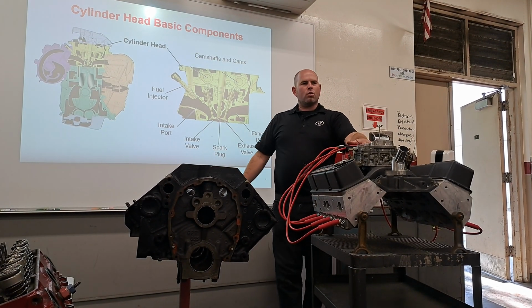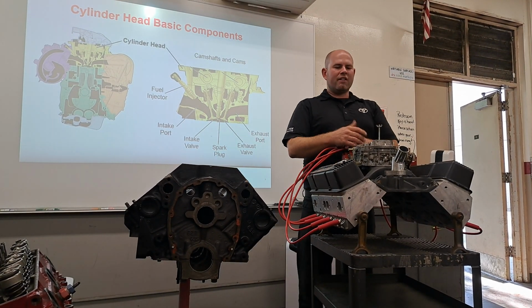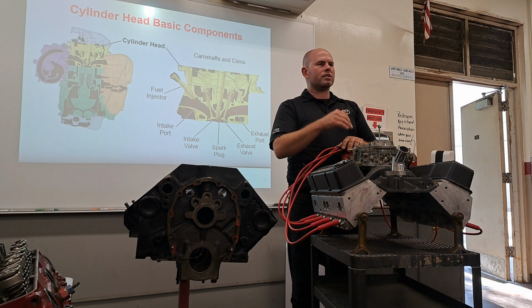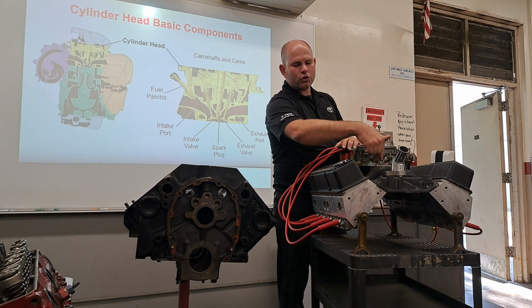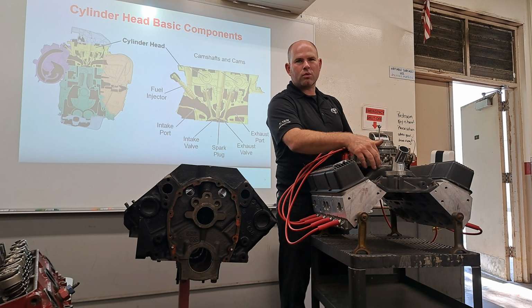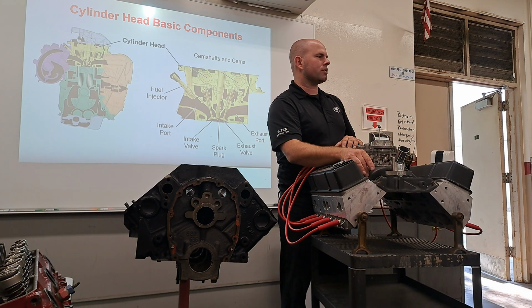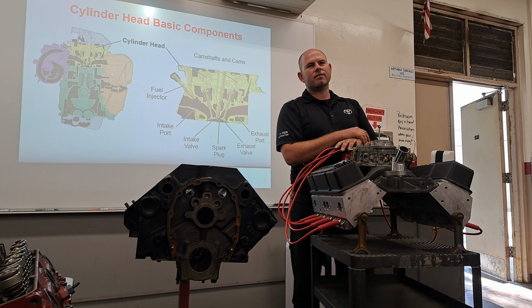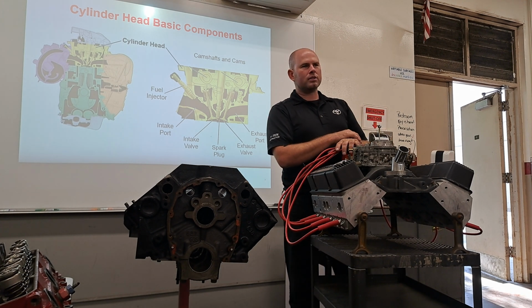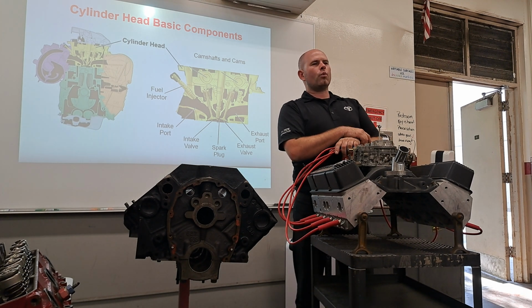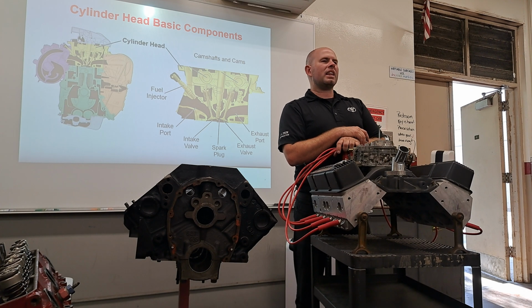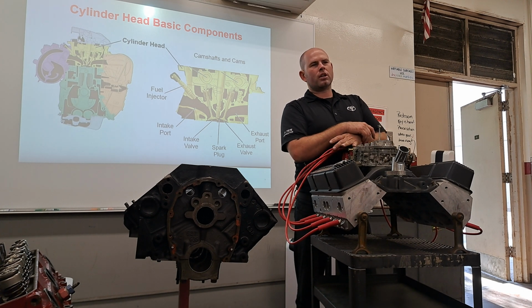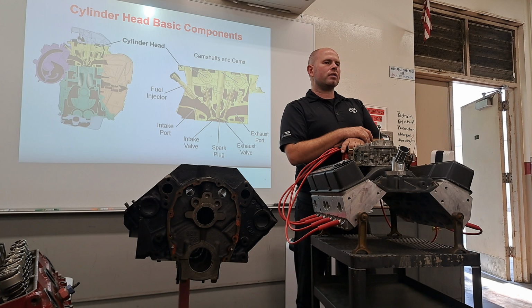You want to know why? If you mix the fuel in ahead of time, you might get little droplets that would condensate on the runners. You didn't burn that gas, did you? Did it contribute to your horsepower? No, which means you wasted it, didn't you? And that increases your emissions and lowers your fuel economy, you see. So carburetors were never real efficient. People like them. I don't.